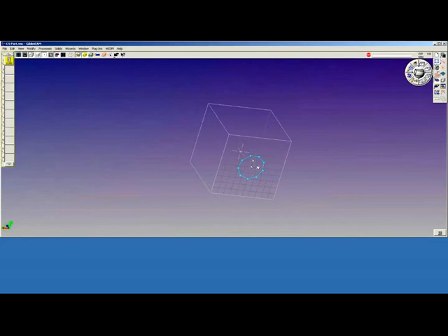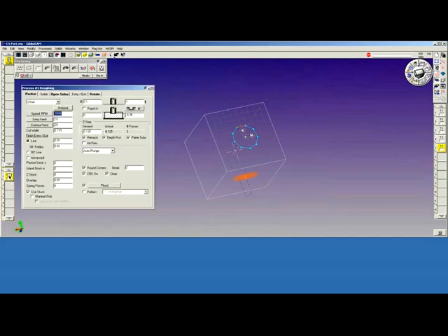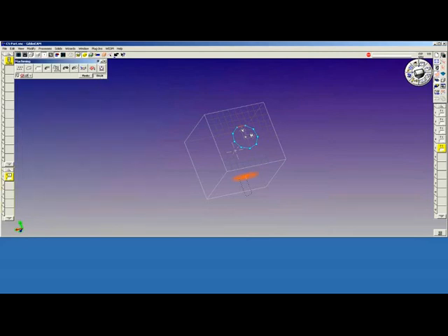Open my tool list, and my CAM list. Select the geometry, and as you know, when you've got a connected shape, simply selecting one portion of the geometry will identify the entire shape. Go to my process dialog, rotate, got to select the bottom CS, and this 90 here makes no difference as long as duplications are 0. I could have any value here and it won't affect anything. But to keep it clean, I'll make that 0. I'm machining in the bottom. Do it.